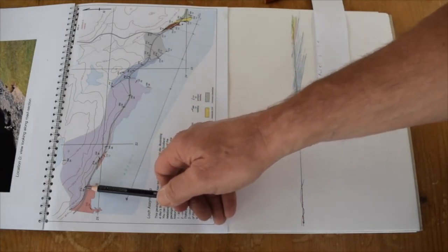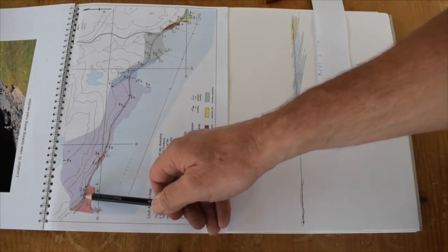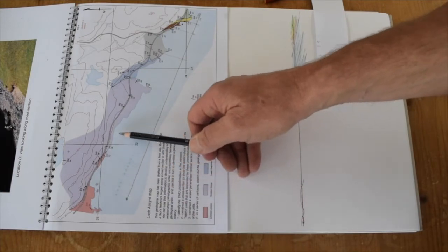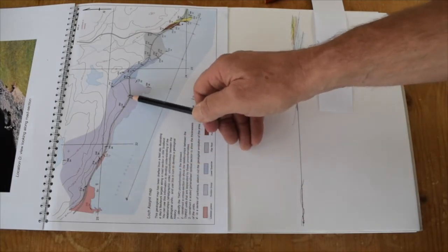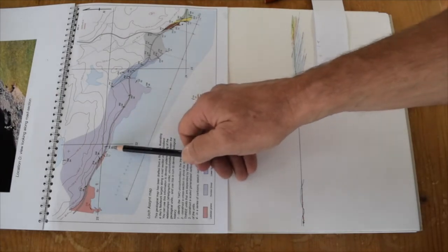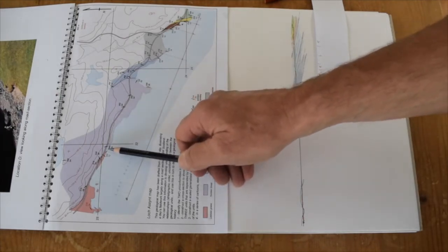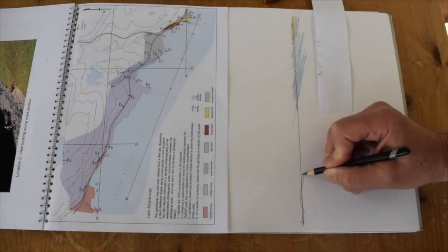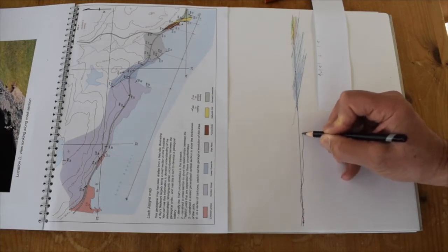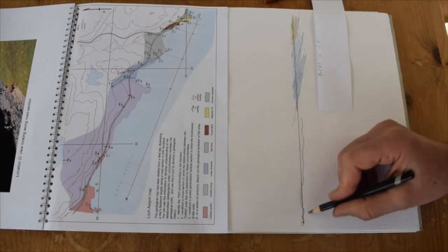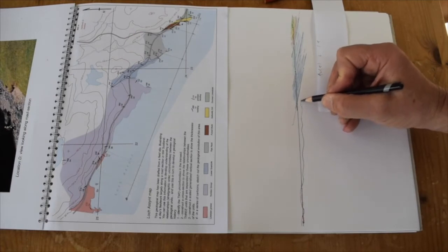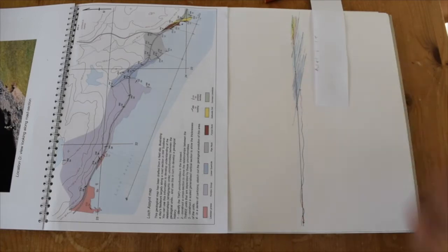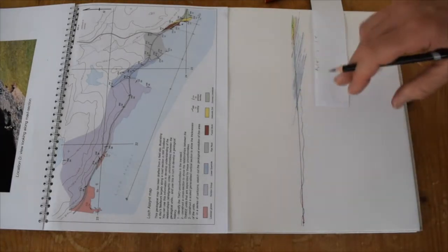If we look in this part, the boundary is just simply running along between 80 and 100 meters, just almost parallel to the road through there, so flat lying-ish. And under here, the beds above are dipping, what, 4 degrees, 2 degrees, 6 degrees, that's really low angle. So if we use these bed orientations as a guide, presumably the unconformity is just below surface. I'll do that. I won't draw it as a straight line, I'll keep it fairly irregular, arbitrarily drawing in some undulations to honour this sort of geometry. And it's going to come along and has to abut here the unconformity at the base of the lower quartzite.